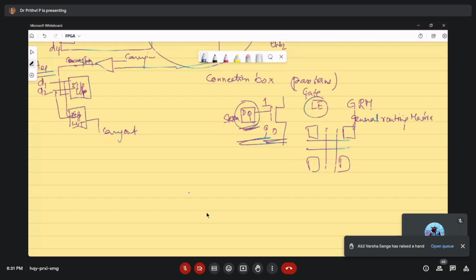Okay, so generally this is something like using hexa lines, or a 12-bit line can be there, or a 24-bit line can be there. Based on the space available, the routing matrix will have that many bits per length available for connecting. A single 24-bit line will connect to the nearest, we can say left, right, up or down. So 12 bits for horizontal and 12 bits for vertical will be divided.